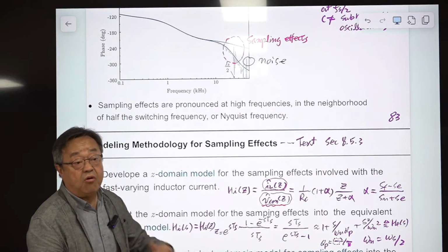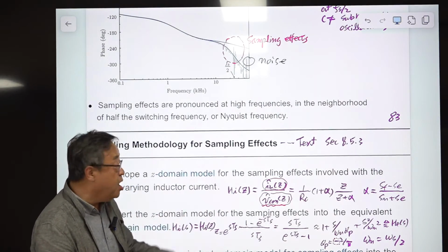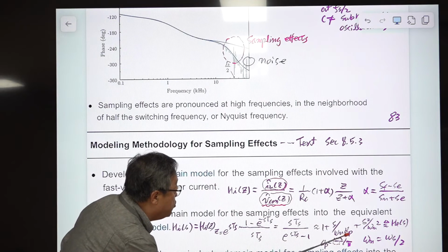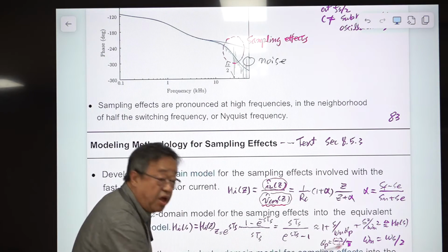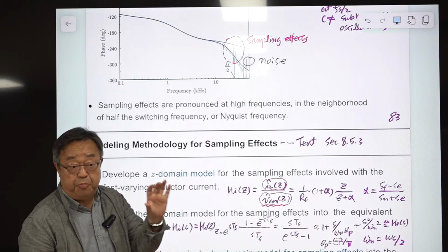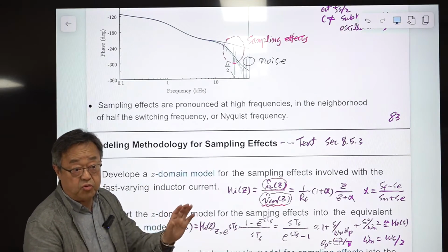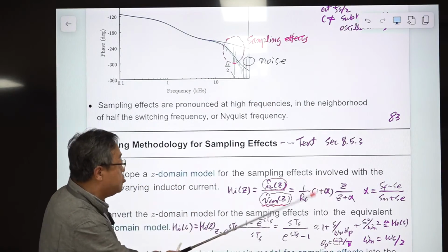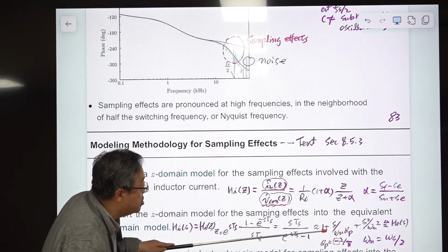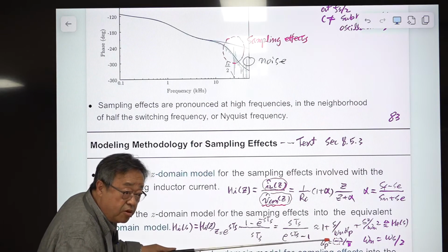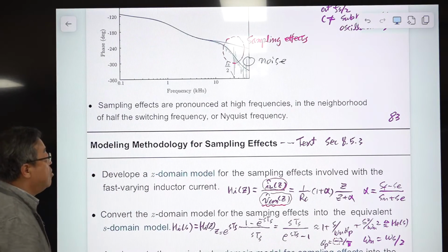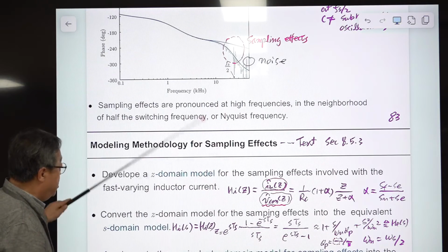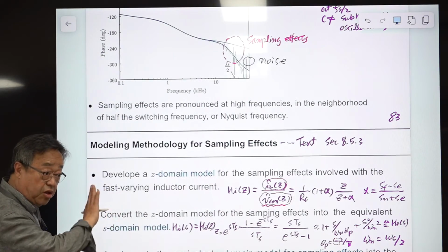So everything occurs at half the switching frequency, and this is a zero, and the Q_p value is negative. This is an RHP zero. You know the RHP and LHP. So there is an RHP zero. So actually this term is negative. This is the result of his model, and he has several other derivations.